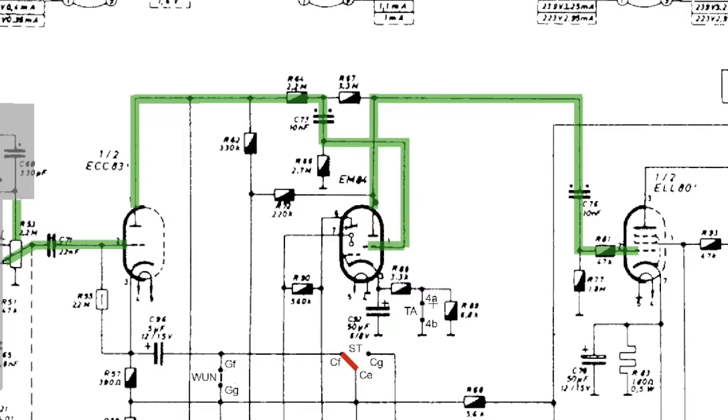It's not shorted to ground because when you activate TA, that switch opens. That switch needs to be open as well. My mistake. So you've got a 6.8K plus 3.3K resistor to ground. That's the cathode resistor. It's bypassed with a 50 microfarad capacitor. So this is a typical triode amplification stage with a gain, in this case, of -1.